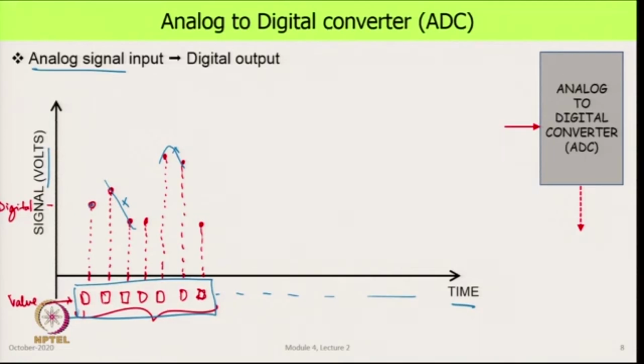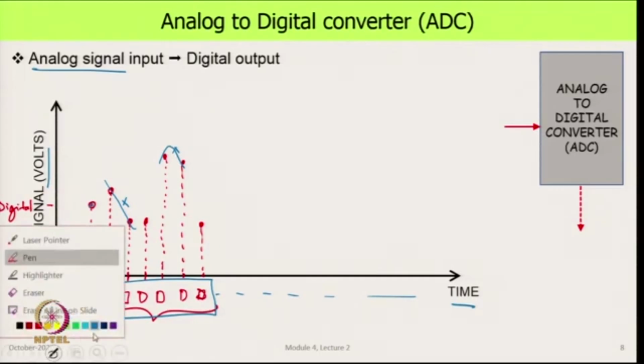So, this is one of the issues that comes up with analog to digital conversion. If you have a very high frequency of conversion, that means the time at which you take these numbers is much more finely spaced than the frequencies in the signal, then we get a very faithful reproduction of the signal itself. And then we can store it and do all types of operations with it. This can also cause serious problems.